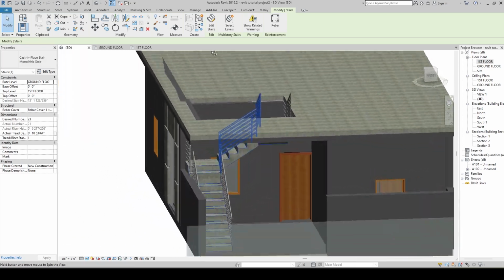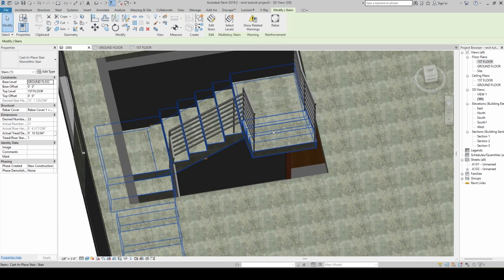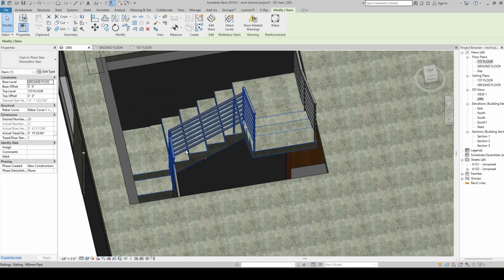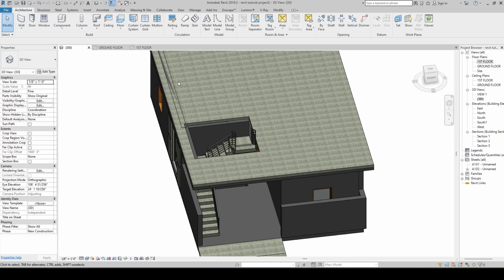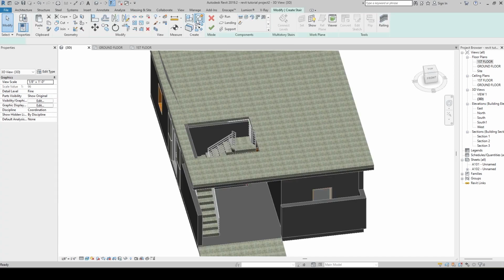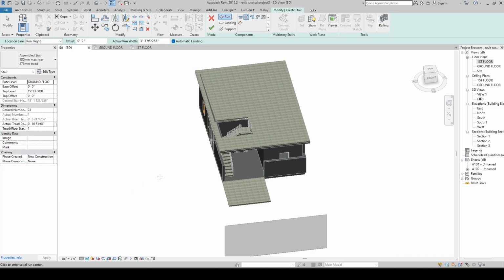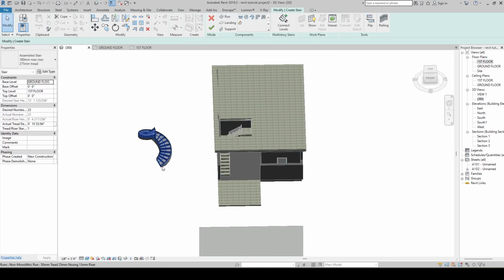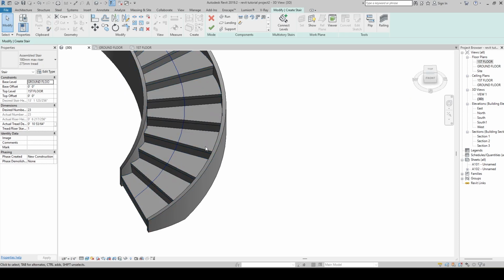So I think this is how the staircase by component is going to work. I have made an extra opening that you can edit in the staircase or the slab. This is one of the methods to place the staircase. There are different types of pre-built components available. If you want, I click on the staircase and there are other types like full step, spiral, and so on. You can place them this way. It takes the ground floor to the first floor with all the dimensions, automatically divides the staircase, and you can look at how it looks.